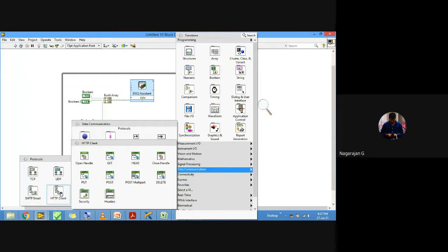That is one more case where you can monitor all the information on your phone itself. If your phone and your myRIO hardware are connected to the same existing network, you can use network shared variables, which help to transfer data from system to system. Through your myRIO hardware, you can share the data to your mobile phone. Your mobile is another target, and your myRIO is another target. Using network shared variables, you can transfer the data and monitor it. For example, if you have a temperature sensor and a small fan, when the temperature is high you can turn the fan on and off through your mobile phone. That is also possible, and for that we need to use a network shared variable.